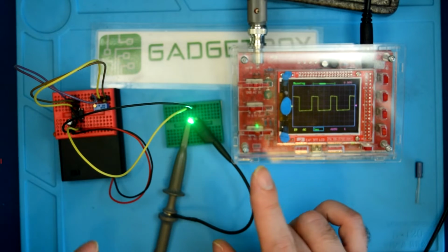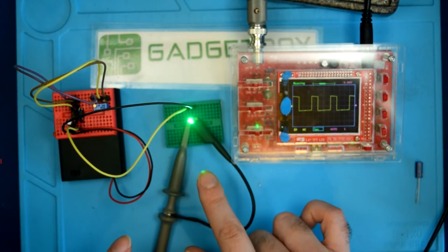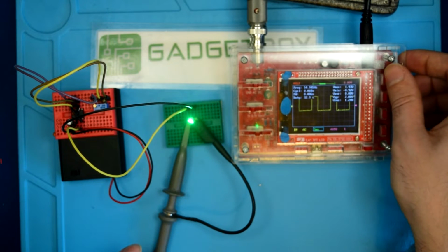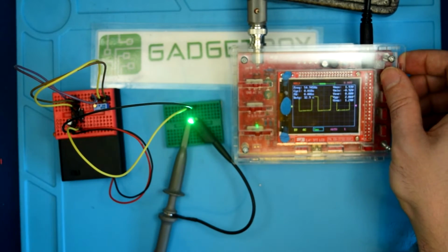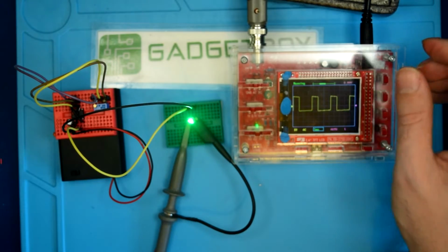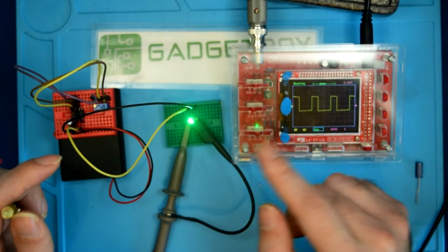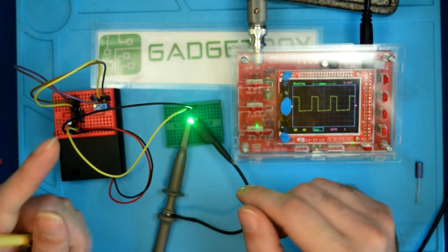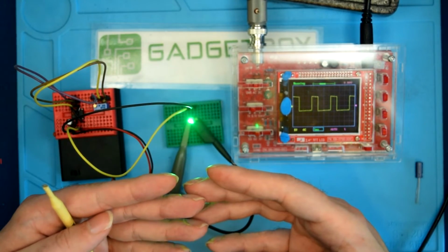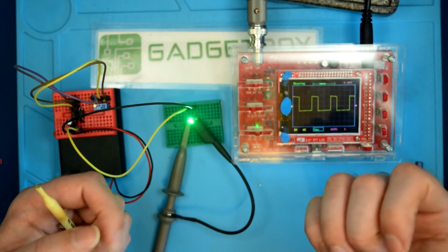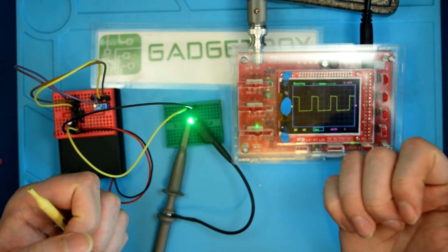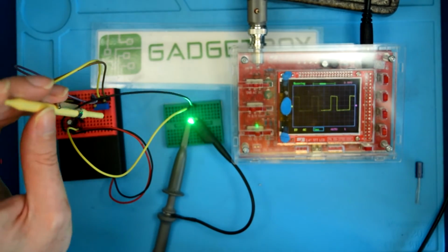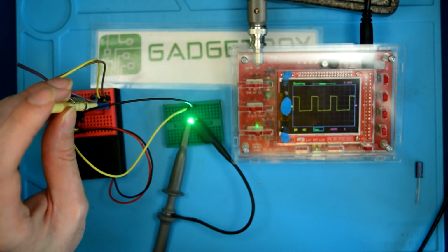Anyway, so looking at this LED, I can't see anything going on. What frequency are we running at? We're running at 54 hertz. But I'm filming, that's 54 times a second. I'm filming at 60 frames a second. So the frequency of the flashing of the LED and the frequency of the shutter are not compatible. So you get this shimmer. And it gets worse if you dim the light.